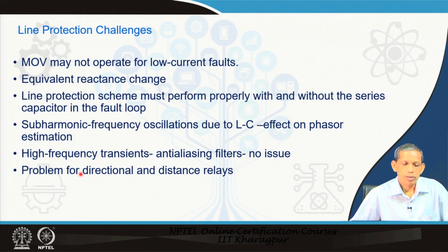The challenges which you will see from the directional relay or line protection perspective are two aspects: one in the distance relay itself, and we know the distance relay also requires directional features, maybe a separate directional algorithm also. So, that component is also affected by the presence of the series capacitor in the circuit. We will like to analyze this. In this lecture, we will address only the directional relay part. In the next one, we will talk about the distance relay.